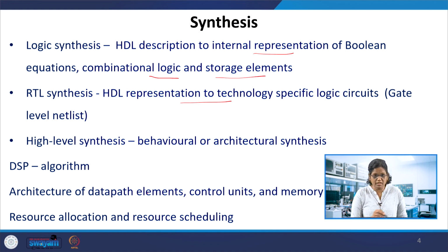In that case, the data path elements, control path and the memory are to be decided, how this algorithm goes through the data path and control path, and also the memory required for this algorithm to be executed in the FPGAs. It is also very much concerned about resource allocation and resource scheduling. What resources should be used and how the resources are going to be scheduled according to time will be dealt with in high level synthesis.